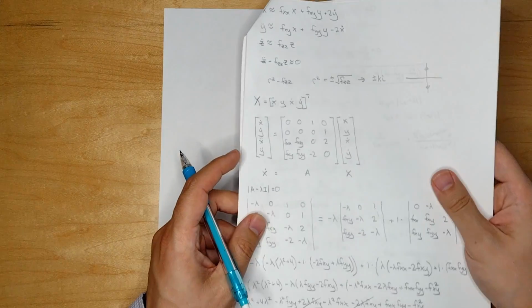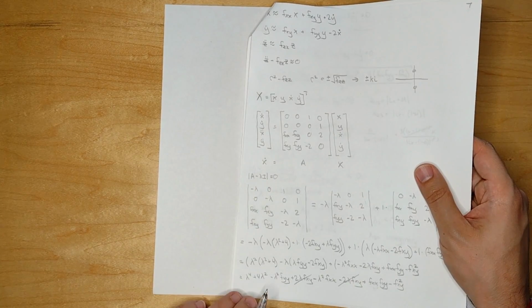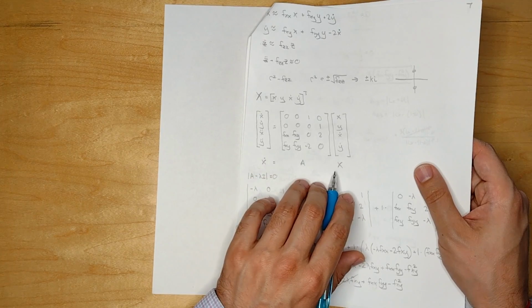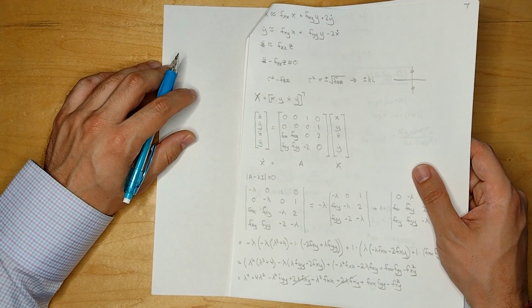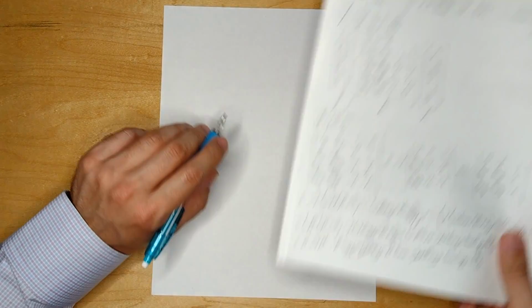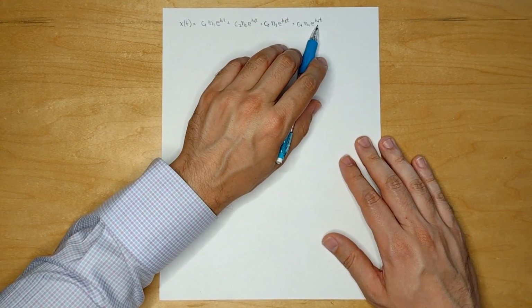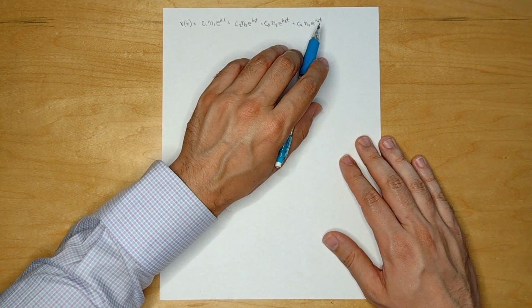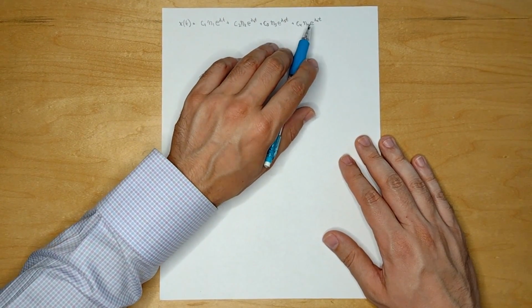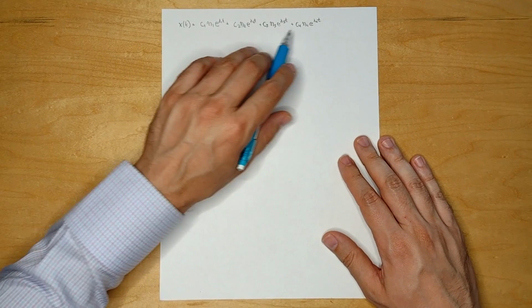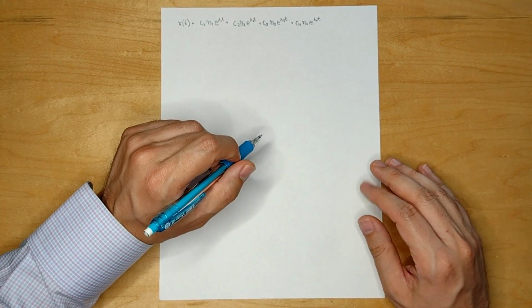In the last lecture, we linearized the system and got it to a form x dot equals Ax. Now, when you have equations of this form and A is constant, you can write the solution in the following form, where lambda 1 through lambda 4 are the eigenvalues of the A matrix from the previous slide, eta 1 through 4 are the corresponding eigenvectors, and c 1 through 4 are constant scalar values that depend on the initial conditions.